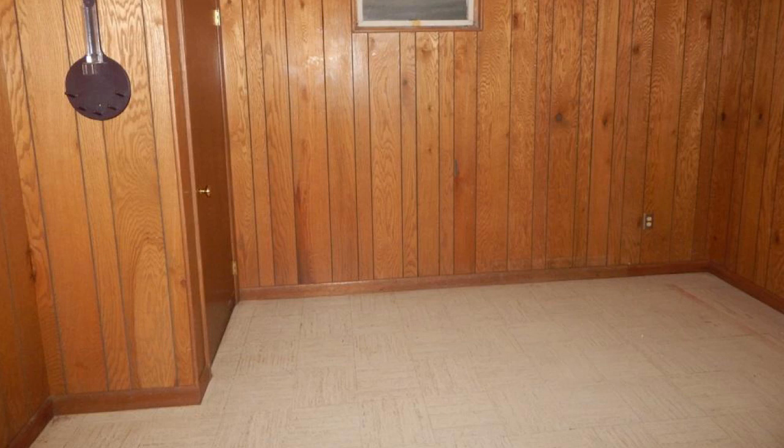The next thing I want you to take a peek at is we go back to this finished room that we have here. The finished room, although everything looked dry, when we look at it more closely, we'll see that when you run your flashlight along the wall parallel to the surface area, that indeed the mold shows up on the wall. Still no water stains, but certainly lots of mold along the wall on the paneling.